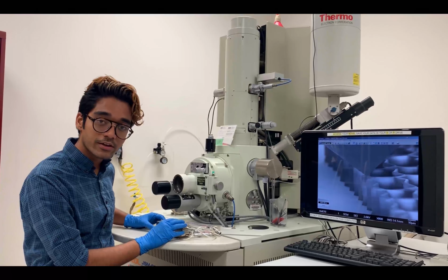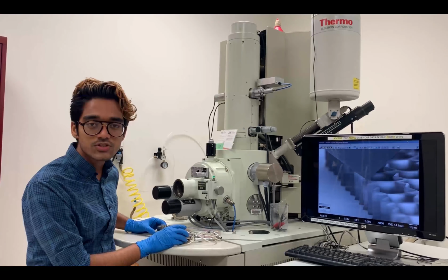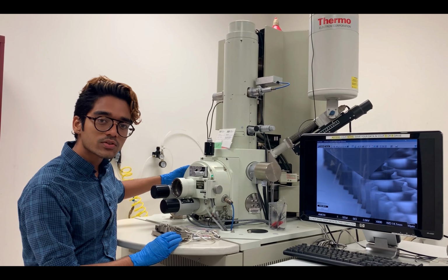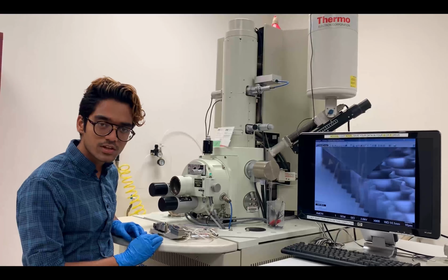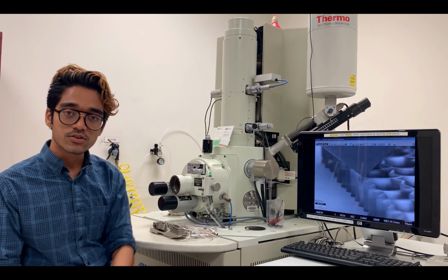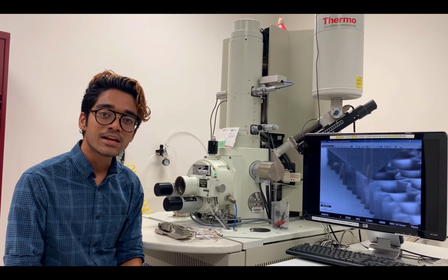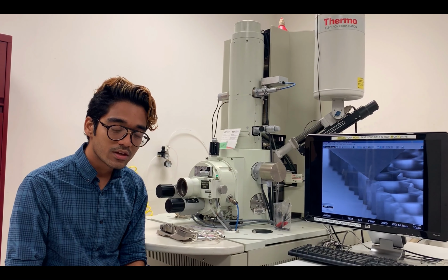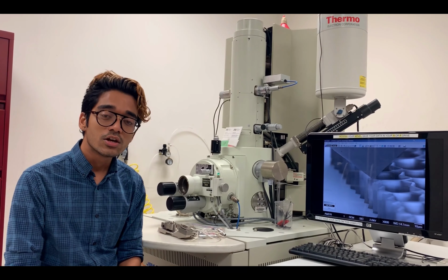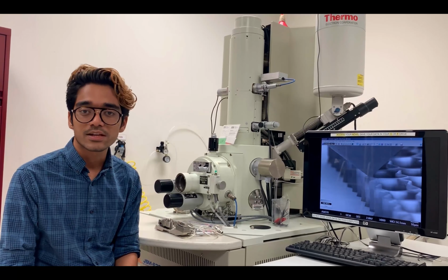We have a tip holder here which can hold different kinds of tips that we use to probe the mechanical response of the material. The stage can be installed inside this microscope chamber so that we can observe the real-time deformation videos as the test is being performed. We can see the deformation in this monitor screen. So for example, right now you see a honeycomb scaffold structure which is being indented inside the SEM. In situ mechanical characterization is a very powerful approach because you're able to extract load displacement characteristics while simultaneously looking at how the material is deforming in real time.